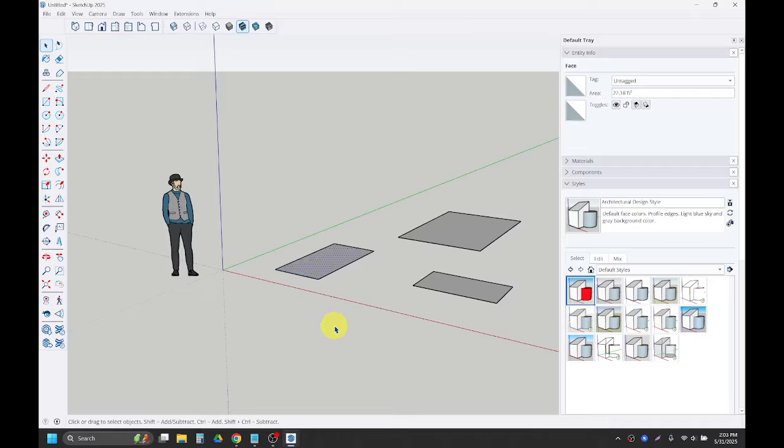So essentially what SketchUp consists of at the moment is just edges and surfaces. And kind of everything within this software is just either an edge or a surface or a combination of edges to make a surface in there. And once you have surfaces made, you then can pull them or extrude them up using the push-pull tool. The push-pull tool is keyboard shortcut P, or this button right here, and then we can click on a surface and we can extrude it or pull it up.